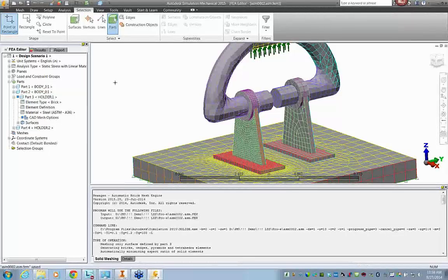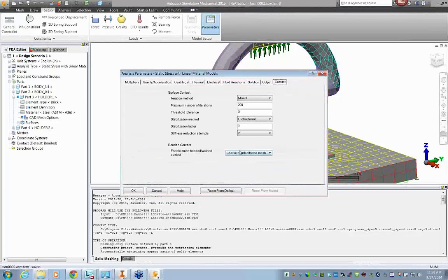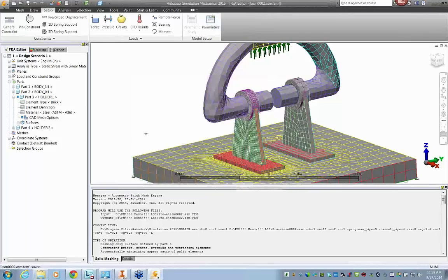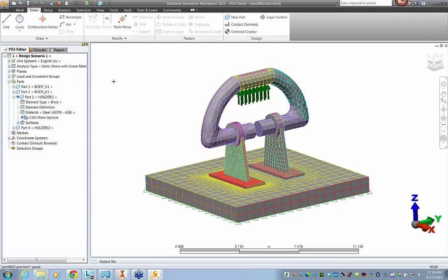And if you do it this way, of course, you don't need any of that. You don't need any of the smart bonding. Right. What you can do is you can visualize that contact grouping. Let me turn this off. And this may be something that not a lot of people know about, which is how to actually visualize that contact condition. In the Draw tab, we have this almost hidden option called Layer Control.